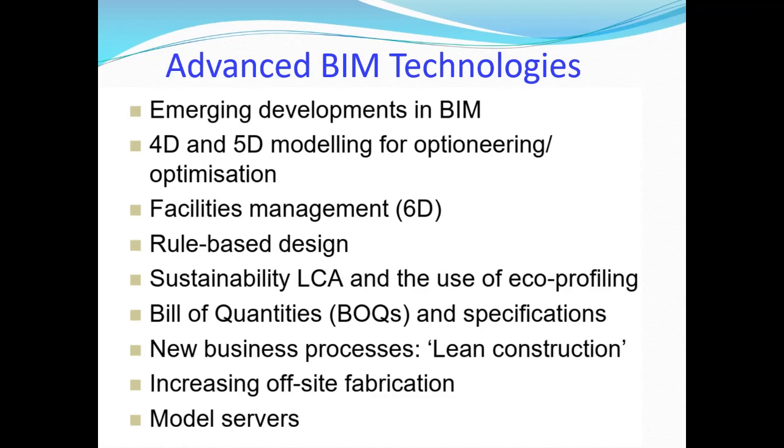So we know the concrete usage index, because we don't want to overuse concrete. So we can monitor our building. If it goes more than 0.4, then we find the reason why. Can we reduce it or not? It's an advance warning sign. So we can go back and look at our structural scheme and find out why our concrete sizes are big. So these models are useful for that purpose.